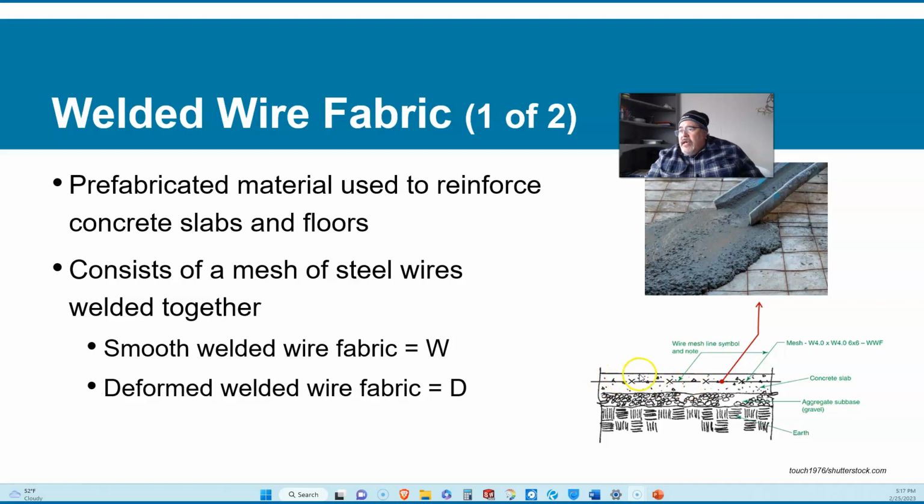So you can see that this space from here to here, from the top surface to the lower level, is roughly say 6 inches in thickness, with the wire halfway in between. So you see this wire laying on the surface being poured with concrete, but what someone will do after is reach into the concrete and lift and pull the wire up and get it to float in the center. That's not always allowed. Sometimes you have to put spacers under the wire to have it already up in the air to be filled underneath.